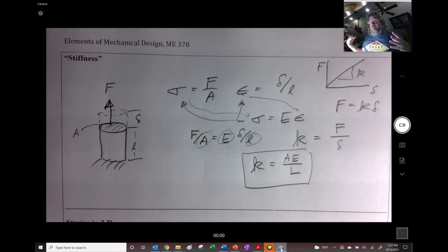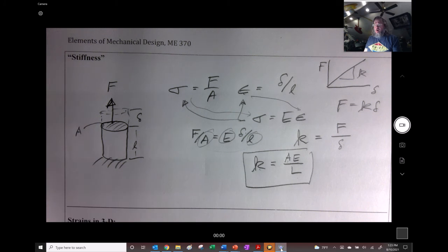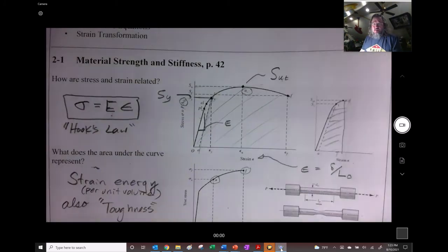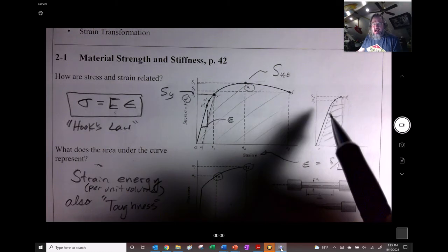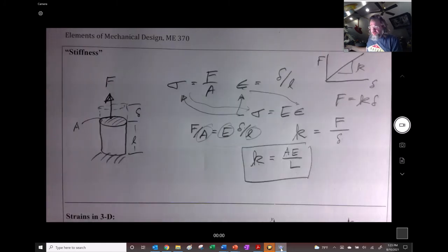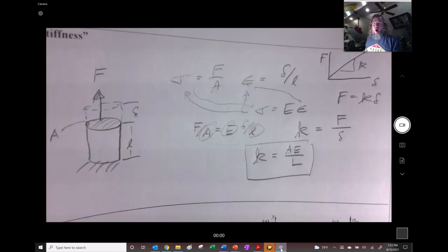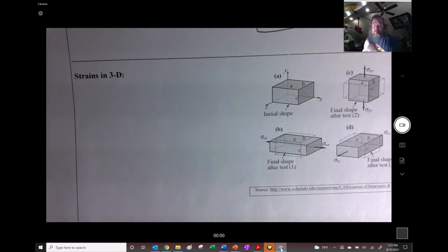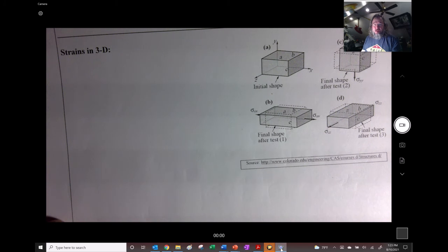So you could think of elastic modulus as the inherent stiffness of a material in the small displacement region, below the yield strength, in the elastic limit type of region. Now, I think it's good to keep that in mind when we're trying to recall these material properties and kind of our memory of what's taking place in the stress and strain relationship. Now, if we want to go all possible directions, we want to extend this uniaxial relationship for stress and strain to all directions.